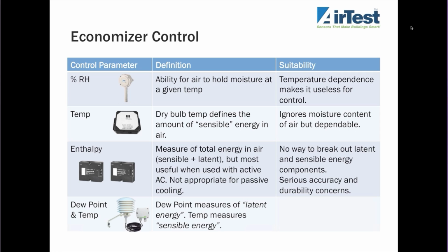One of the other issues about enthalpy sensors is there have been a number of independent studies that have questioned their accuracy and durability concerns. In fact, even if you take a look at the data sheets for most enthalpy sensors, you will see that they don't even state the accuracy of the sensor.